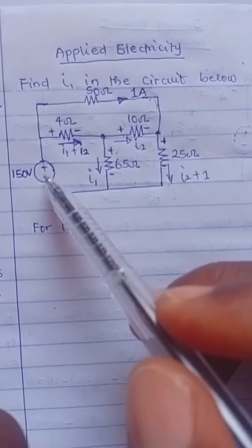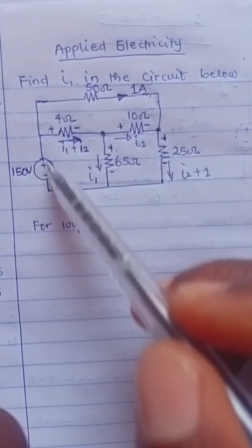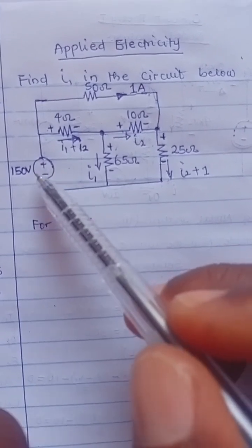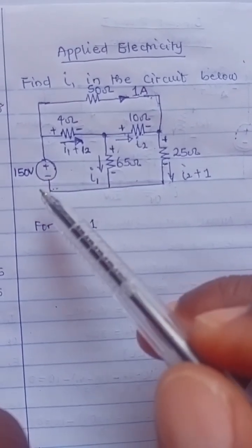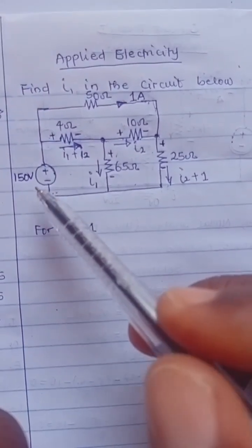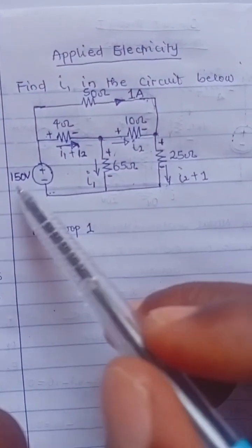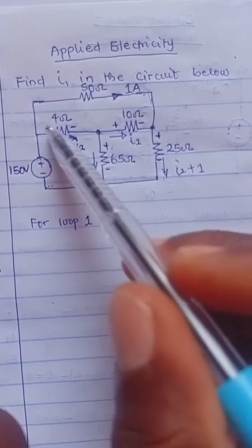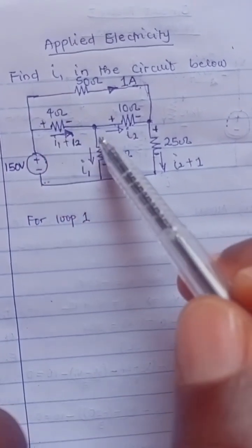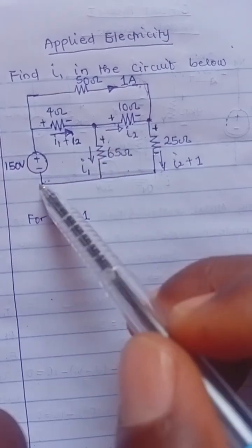That is, if the first thing we see for that voltage source or that voltage drop across that element is the negative sign, then that would be the sign for that voltage. So this is going to carry minus 150 volts. This is going to carry plus, because remember we are going like this. So the first thing I encountered here was plus. Then this is going to carry a plus as well. Then back to where we started from.